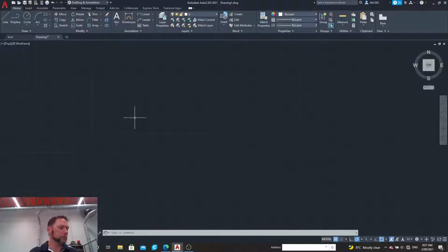Okay, so in my drawing, I've decided to make the framework 950 by 400 mils, so 950 mils long and 400 mils wide. So first I'm going to draw that. So I start with line. Oh no, first of all I have to set up. So I've set up my layers. I've got 4 different layers, and I can select which layer I want.